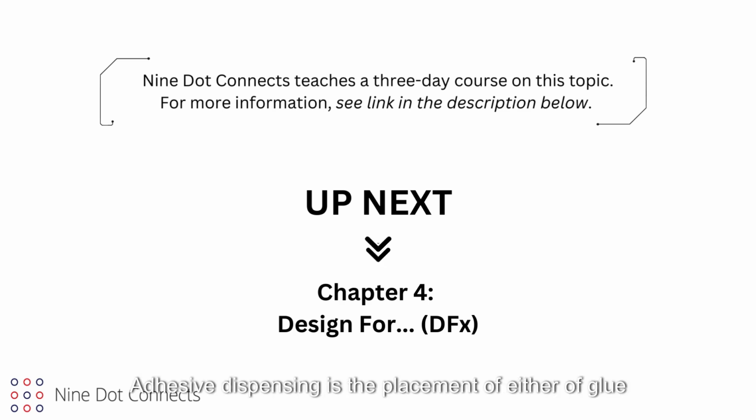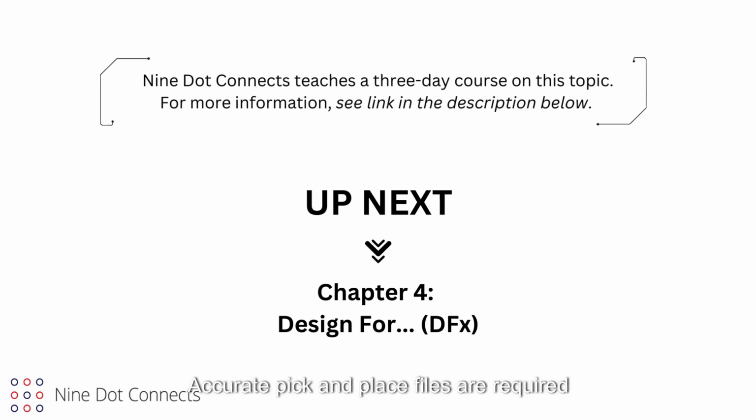Adhesive dispensing is the placement of either a glue dot or solder paste to hold the mounted device until adhesive cure or soldering. Accurate pick and place files are required to automate the device placement. Adhesive curing is often called pre-cure. It's used to increase the viscosity of the glue or solder before reflow soldering or wave soldering.